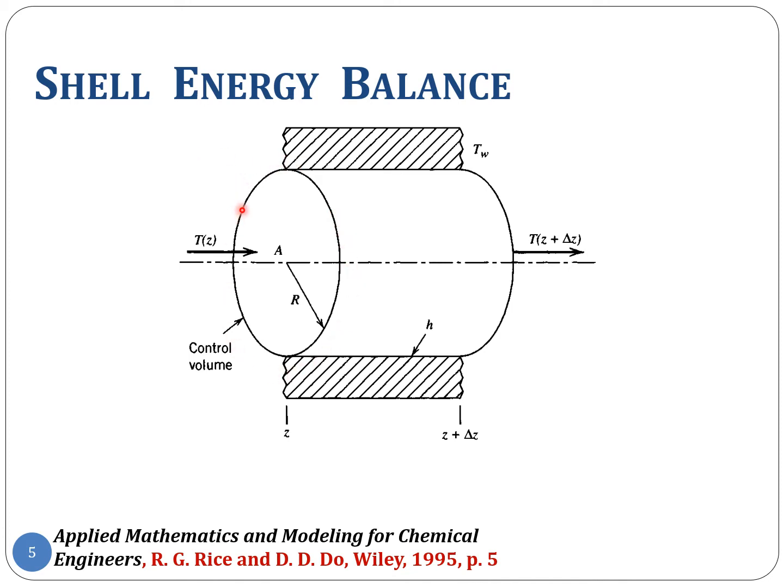the hot fluid temperature, if you are interested in it from the hot fluid perspective, or the same as the cold fluid temperature if you're interested in that. So in effect what we are saying is that the thickness of the wall itself is so small compared to the radius that it is negligible. So we are just going to consider one cold fluid temperature and one hot fluid temperature, and that's it. We are not going to bother about defining any temperatures in between in the wall.